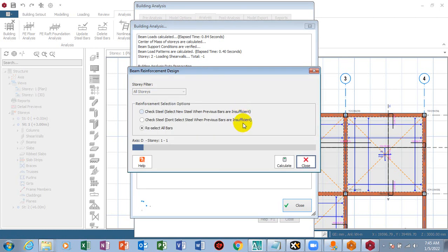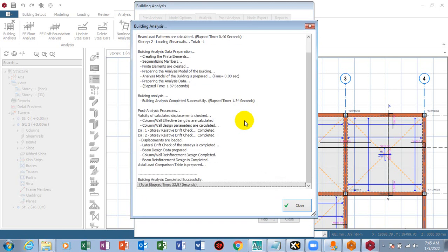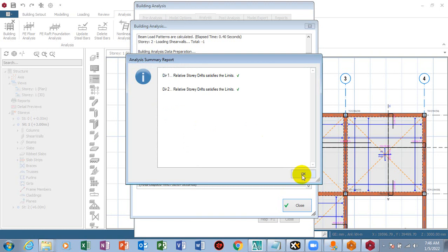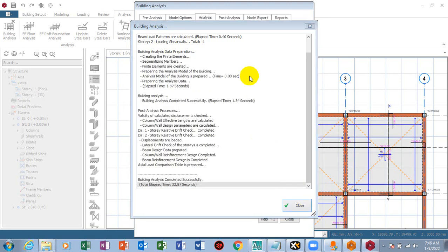So that's why it's called design. You increase the depth. If you were using 450 depth, increase it to like 500 and try. When you have a very large span, let's say your span is already exceeding 5.5 meters, it is advisable you increase the depth to like 550 mm. Or 600 is a bit much, but 600 is on the safer side. Yeah, 600 would definitely pass, but it's not going to be economical.